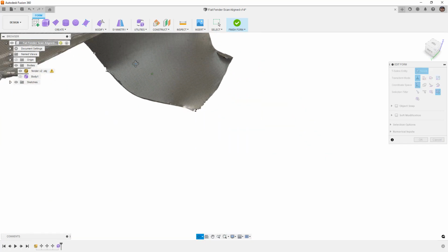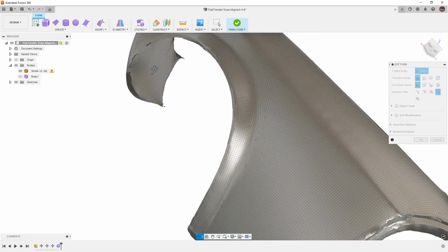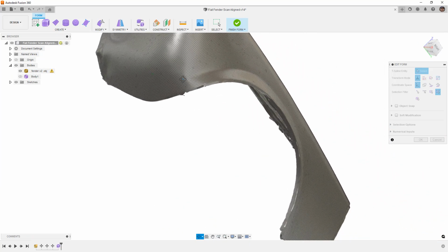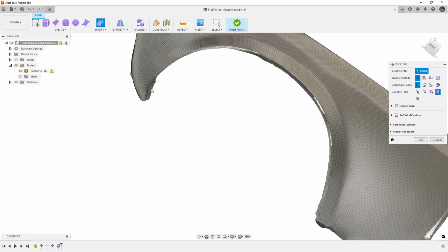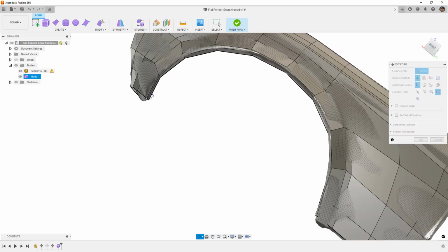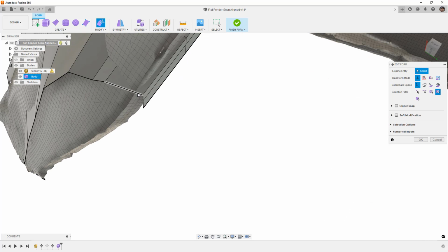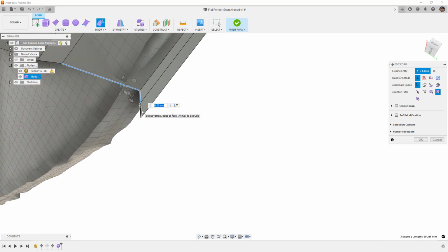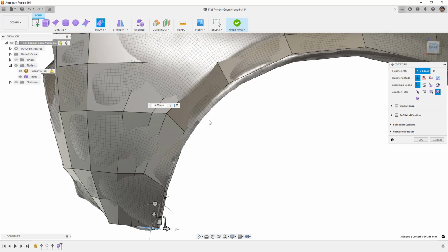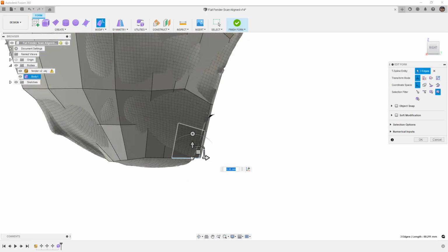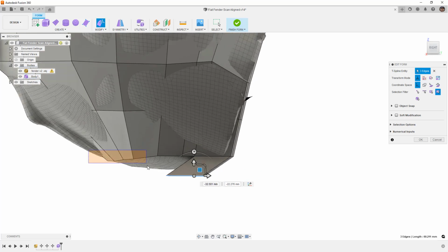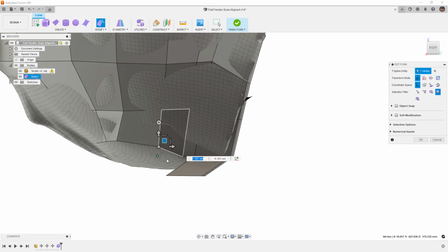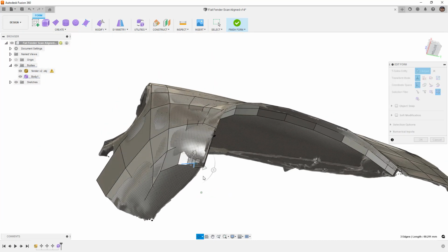So that's what it looks like to me, just looking at the scan. Now there's an inside of the scan that is kind of filled in, probably as a result of the scanner itself. So I'm not 100% sure, but it appears to me that that lip is carried down. So what I want to do is take these three faces, carry that lip geometry that we already have, and extrude it a bit. And then I want to take the rest of these edges and pull them up, because I'm going to take this entire bottom edge and just continue to carry it forward.